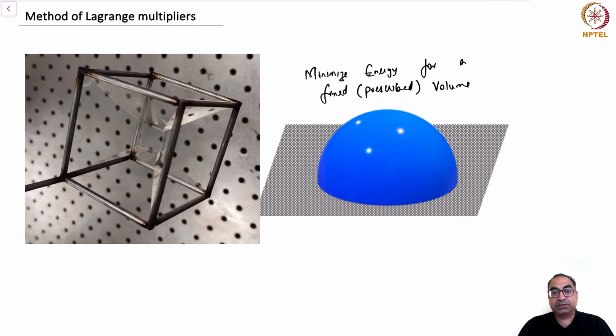In the previous set of lectures, we determined the shape of a static meniscus using two different approaches. One was the force balance approach, and the other was an energy minimization approach. In particular, in the energy minimization approach, we showed that there is a quantity which we can conveniently call the Lagrangian, and this quantity has to satisfy the so-called Euler-Lagrange equations. This quantity, the Lagrangian, or a function f as we called it, is the sum of the surface energy and the gravitational potential energy.